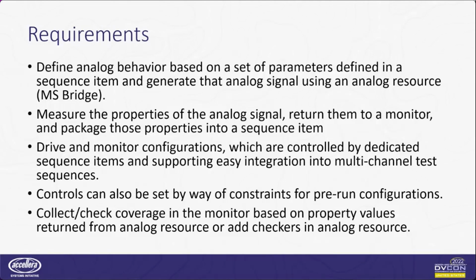And then we also want to be able to collect and check the coverage based on these property values from the analog resource as measured, or potentially add additional checkers in the analog resource, some way of measuring what's going on and turn that back into information that we can use in coverage collectors, scoreboards, or what have you, back up in the class-based environment.